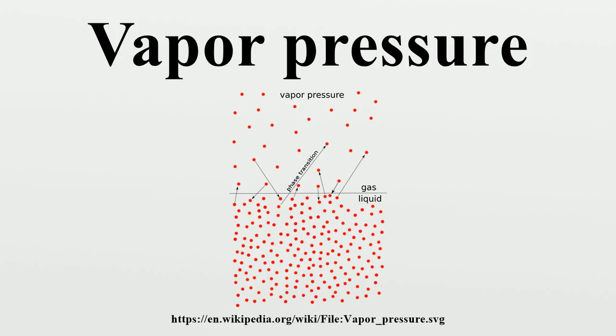The atmospheric pressure boiling point of a liquid is the temperature at which the vapor pressure equals the ambient atmospheric pressure. With any incremental increase in that temperature, the vapor pressure becomes sufficient to overcome atmospheric pressure and lift the liquid to form vapor bubbles inside the bulk of the substance. Bubble formation deeper in the liquid requires a higher pressure, and therefore higher temperature, because the fluid pressure increases above the atmospheric pressure as the depth increases.